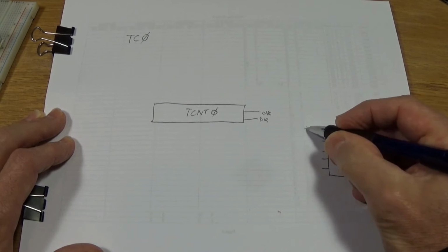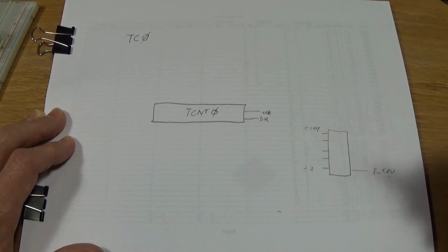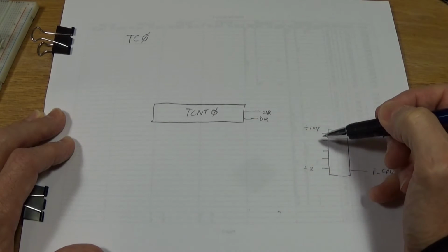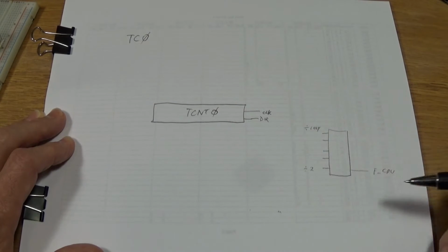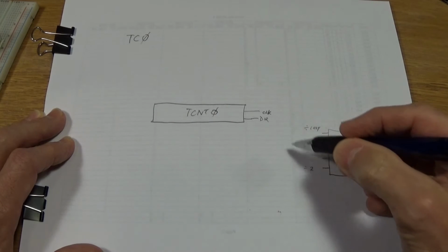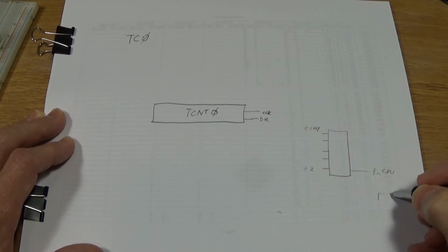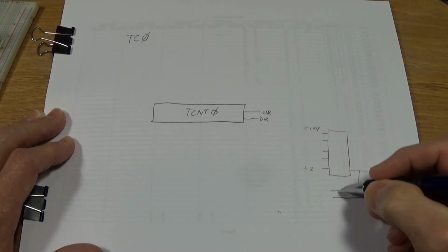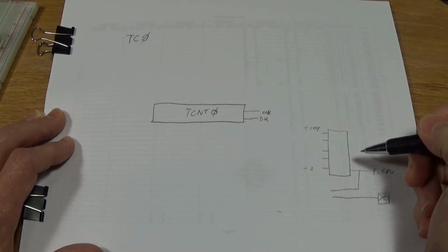So, and then this one might be divide by 2. I have to look it up in the data sheet to figure out what these are, but it's irrelevant at this point. And when you set up the timer counter hardware, you select one of these taps, or you select FCPU directly into the clock, or the external I/O pin. So you have an I/O pin here, and that can go in as well as FCPU. So you have all these different options for incrementing and decrementing the timer counter.